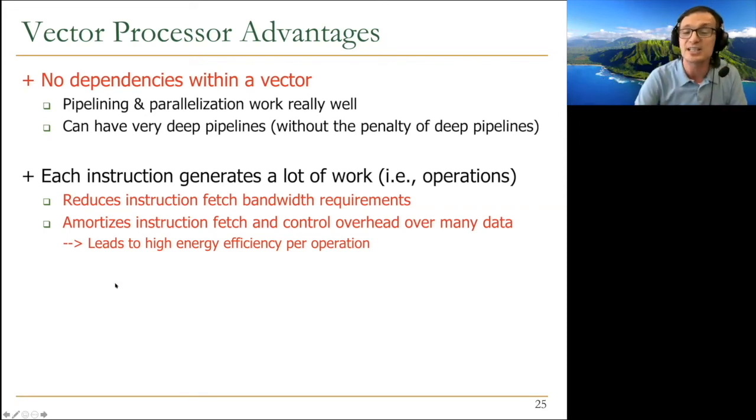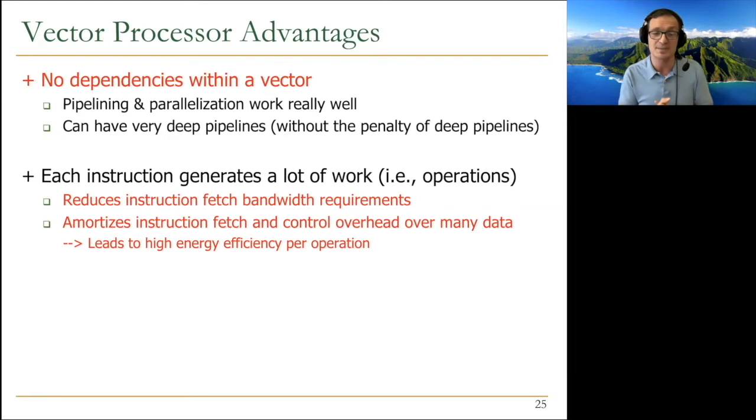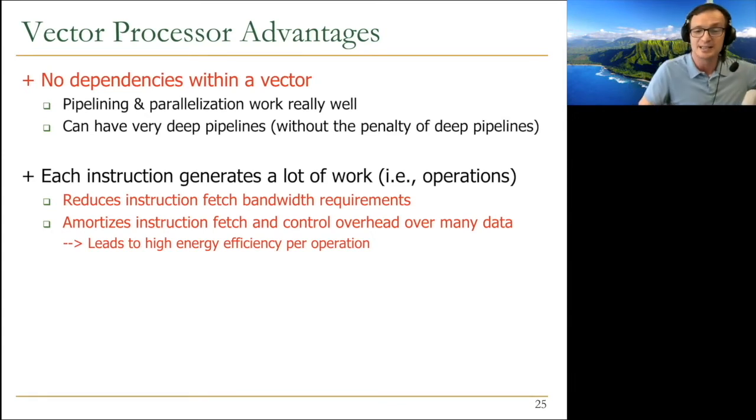As a result, this leads to high energy efficiency per operation. So SIMD processors like GPUs are extremely energy efficient if you're doing the SIMD operations, basically. This is the reason, because you amortize the control overhead, instruction fetch overhead over many, many data elements.